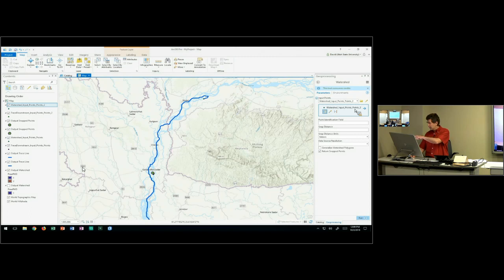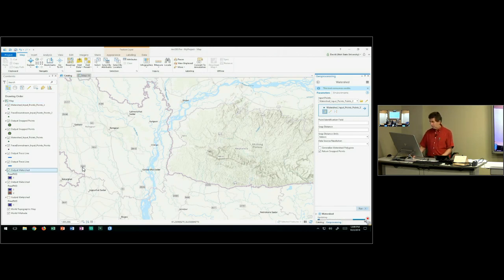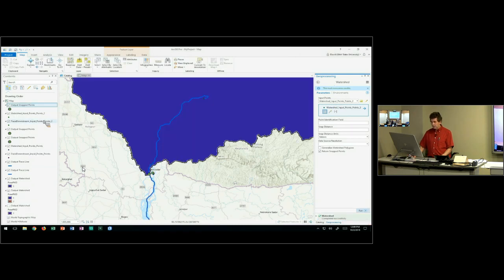You have to click here till you get this watershed input points display to open, and till your mouse cursor is showing a green dot, so when you click it's going to make a point. Click on that flow path there, and now if I run the watershed delineation, I should get the watershed of the Brahmaputra.